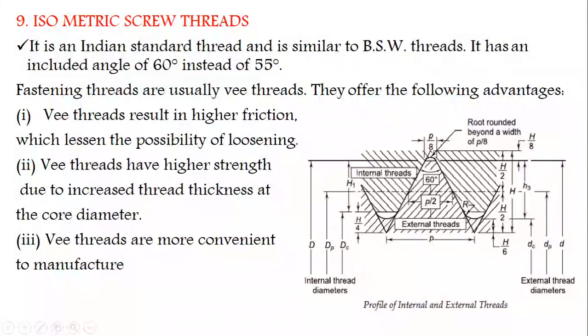The fine threads offer the following advantages. The fine threads have greater strength when subjected to fluctuating load. The fine threads have greater resistance to unscrewing as a result of lower helix angle.